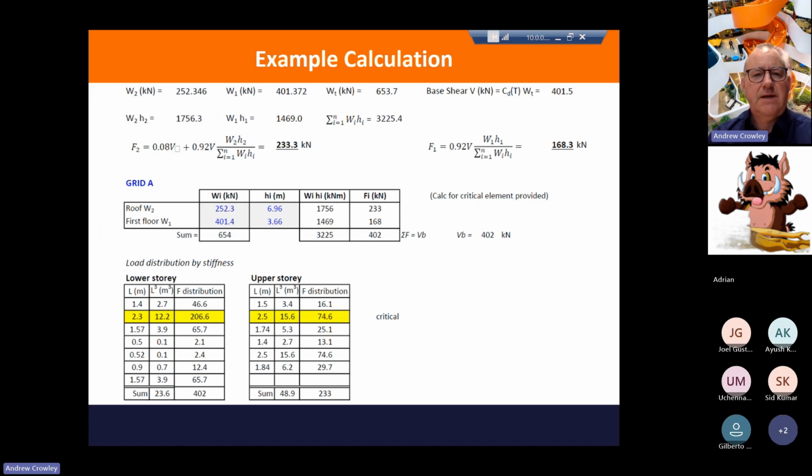And this is quite an old calc that I've pulled out of the archives, and you get some nice neat calculations to show what the forces are in each of the walls when subject to seismic loads. Now this is for one set of walls on one grid line when subject to a seismic force in one direction. So this is quite happily ignored accidental torsion.